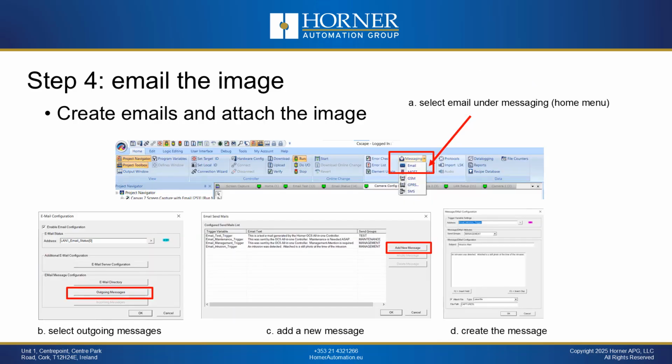In step 4, the captured image will be sent via email as a notification to designated personnel. This allows relevant individuals to be informed of events such as operator logins, unauthorized access attempts, or after-hours incidents. It is important to note that not every screen capture or still image needs to be emailed. For example, capturing an image each time an operator logs in does not necessarily require immediate email notification. However, certain situations will warrant sending the image via email for prompt awareness. We will explain how to ensure that the captured image is attached to an email notification.